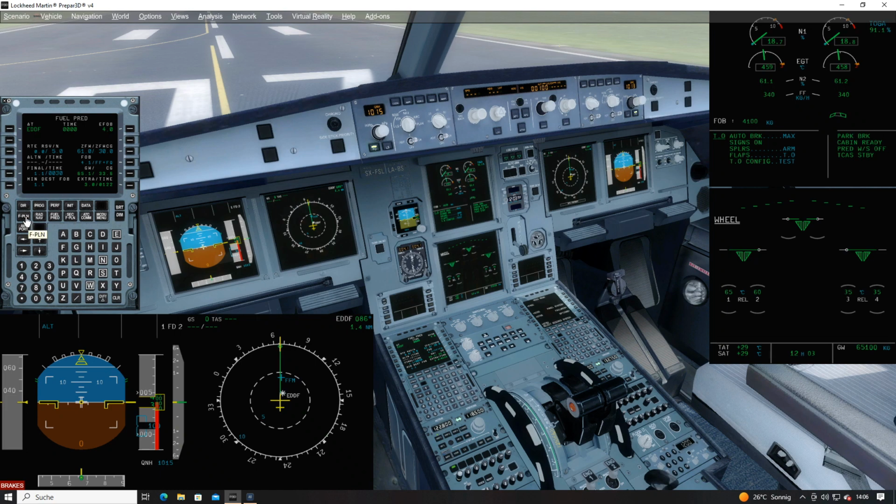We take a runway on the flight plan page. We depart out of runway 07 center. All lateral changes are on the left-hand side of the flight plan page. So I choose here the left-hand side, departure, take 07 center, and then we take the SOBRA 5 Delta, which is 7 Delta. Hasn't changed much. Should be the same. Then insert the temporary flight plan.